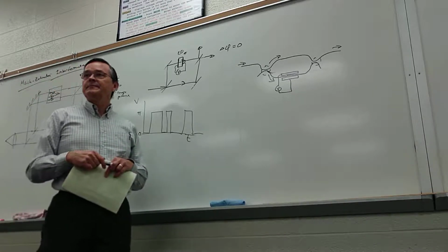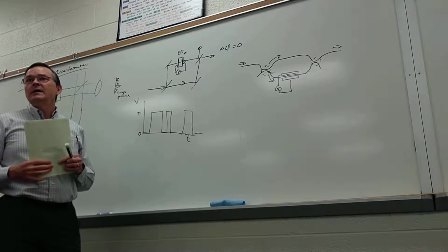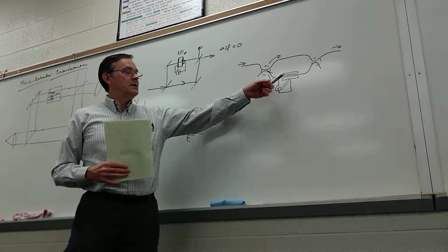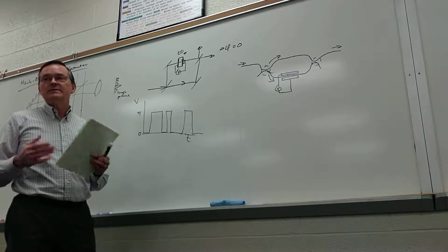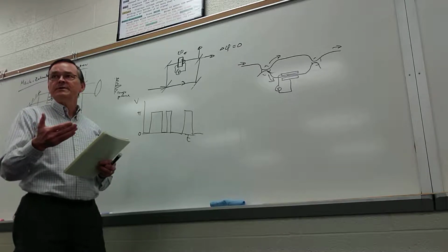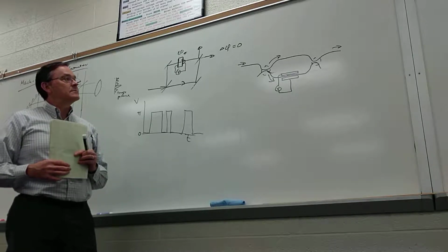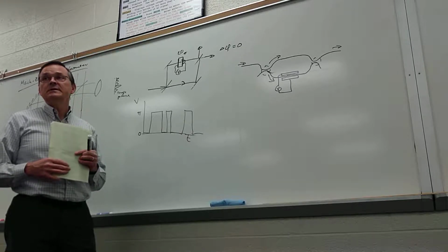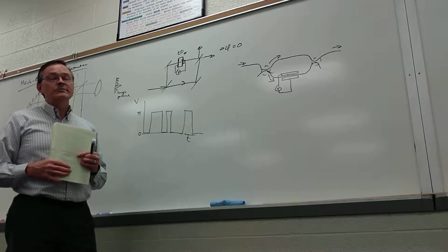Yeah? Sorry, maybe this is a dumb question, but what are the properties of an electro-optic material? It's basically the refractive index seen by the light propagating here is a function of the electric field applied across the material. So that is what an electro-optic material is. So by applying a voltage, meaning an electric field, you can change the refractive index. Is it linear or does it depend on the material? Well, yeah, there's a lot of material dependent things going on. Turns out it's also polarization dependent. But when you dig into all of that, bottom line is, yeah, you can make really fast modulators.